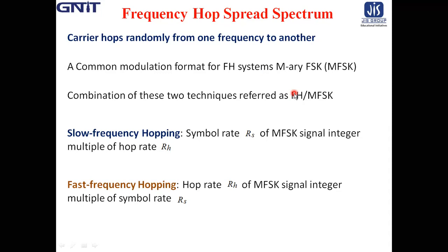In the type of spread spectrum system discussed earlier, the use of a PN sequence to modulate a phase shift keyed signal achieves instantaneous spreading of the transmission bandwidth. The ability of such a system to combat the effect of a jammer is determined by the processing gain of the system, which is a function of the PN sequence period.